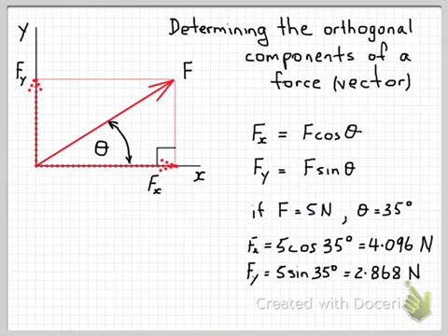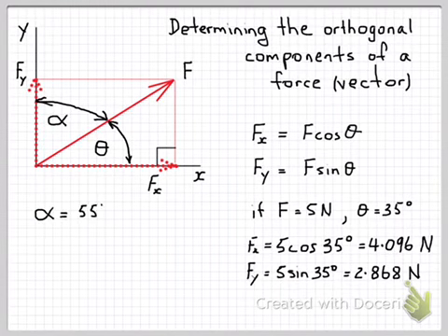Note that the force is not always defined relative to the x-axis. Sometimes you might find that the force is defined relative to the y-axis or some other axis, and so therefore you need to interpret the angles and the trigonometry from the right angle triangle in order to correctly calculate the components.